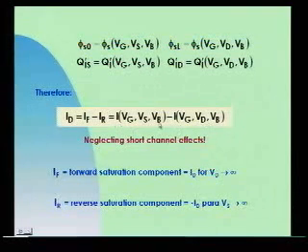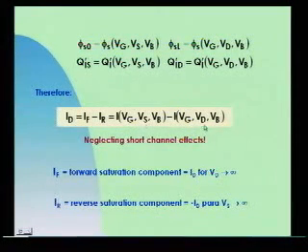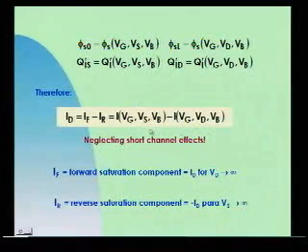These two components have the same functional form, and the only difference is that one is dependent upon the source voltage and the other is dependent upon the drain voltage. If you neglect the short channel effects, sure, after we put the short channel effects, we cannot do this. But we use this as a core model and we add the short channel effects afterwards.